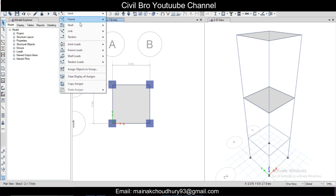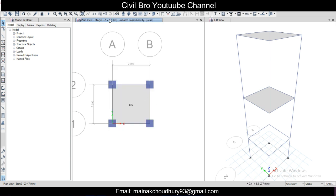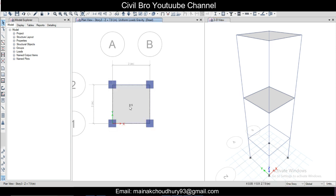Assign, shell loads, uniform loads, dead, and this will be in the gravity direction for the floor finish 0.5, apply and OK, and then we'll select this again now and just assign. So we'll go to assign and shell loads, uniform, and this time for the live load. So I should have put the previous load 0.5 in other dead load. So I'll just press Ctrl Z until this disappears, and then I'll select the shell again.